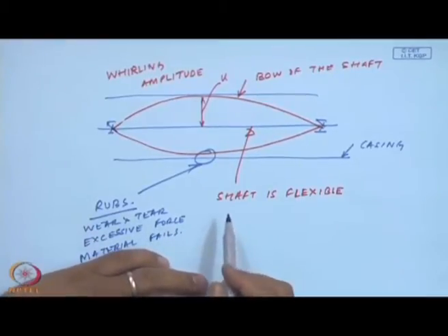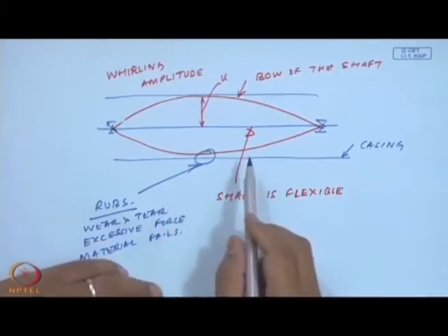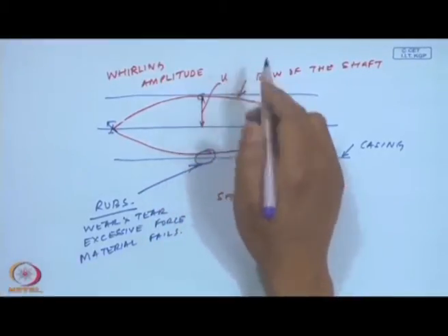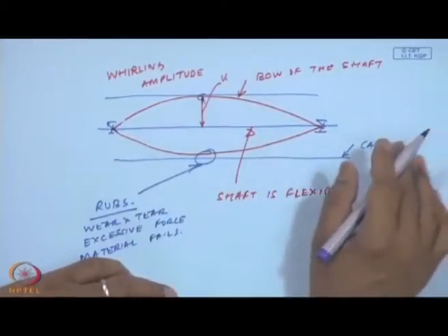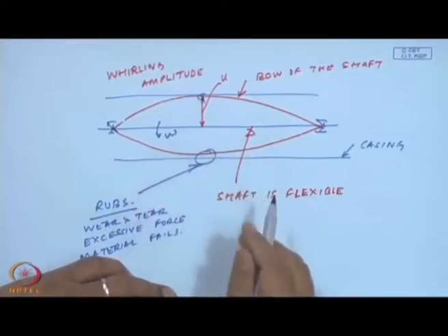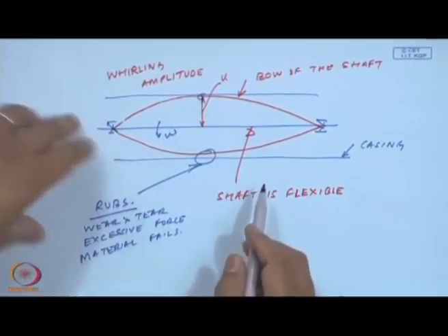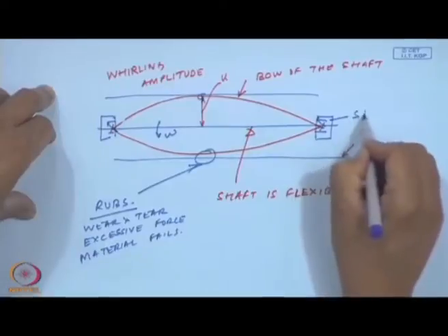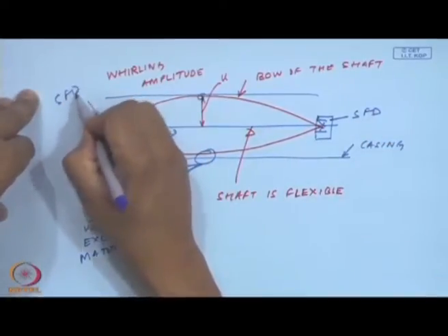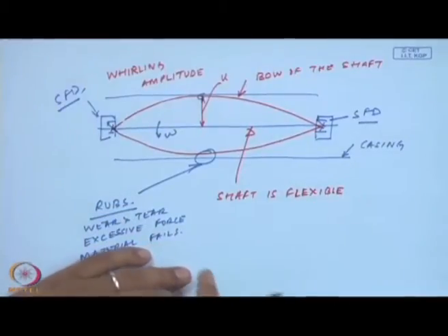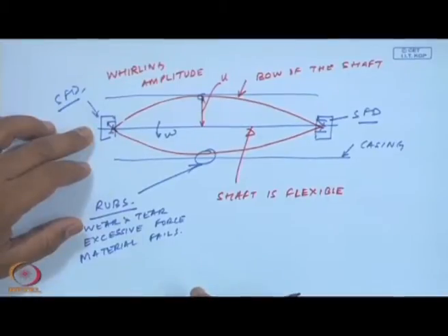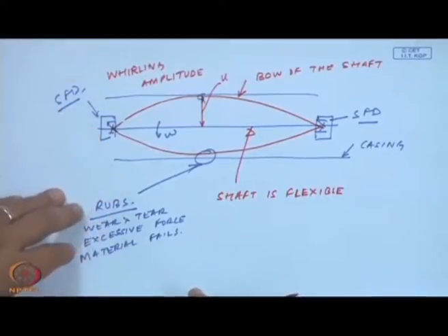Okay, as I was telling you, to reduce the synchronous whirl amplitudes, I have to balance the rotor, so that this unbalanced mass is a minimum, so it does not fly out, or avoid rotating at that particular speed omega. Try to change the speed, and if nothing is possible at these bearings, we can use SFD so that the support forces onto the bearings are going to reduce.